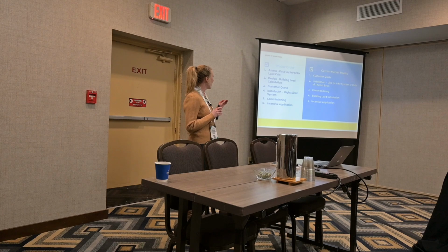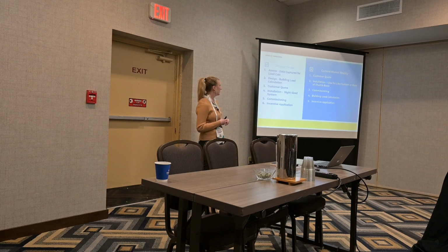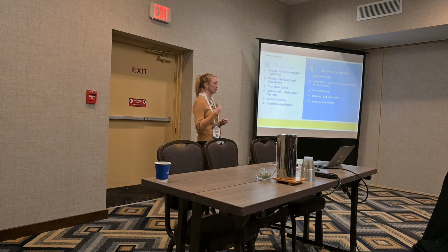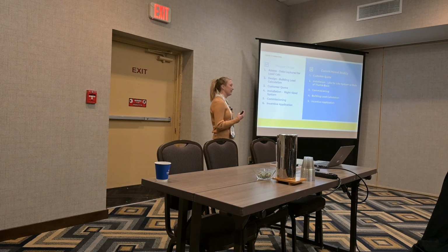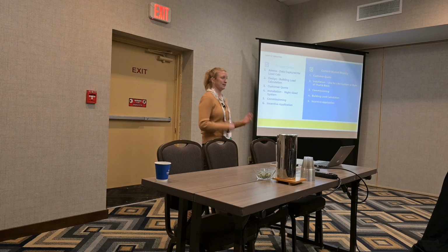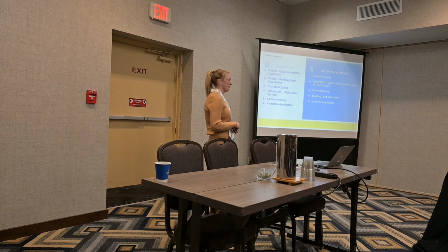So talking about proper order of operations, before number one would actually be air sealing and insulating the home, bringing that load down, then assessing the home to capture all of the building information to perform the load calc, conducting the load calc, getting that customer an accurate quote, and then installing and commissioning a right-sized system. And then hopefully, later in the process, after you've properly sized the equipment, is when you're applying for the incentive application.